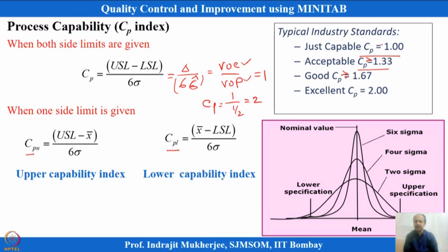Okay. And if it is excellent, if it is more than 2, it is always excellent. So, process capability, if it is greater than or equal to 2, in that case that is the most favorable scenario and we can say excellent performance for the process. Okay. So, this can be calculated and this will be done automatically. Like the philosophy of Six Sigma, which we will discuss afterwards in some of the sessions, it says that the higher the capability, the better the process condition, and less variation, so less rejection basically.